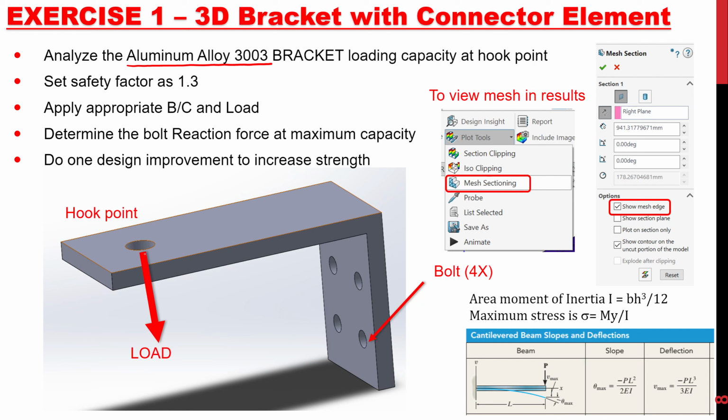You can find this typical bracket probably if you look at any fire extinguisher. Fire extinguishers have all these brackets and then they mount on these brackets. So let's say we would like to set the safety factor as 1.3, and you need to apply proper boundary condition and load. So the objective of today is we would like to find bolt reaction force, meaning if you put 4 bolts here,